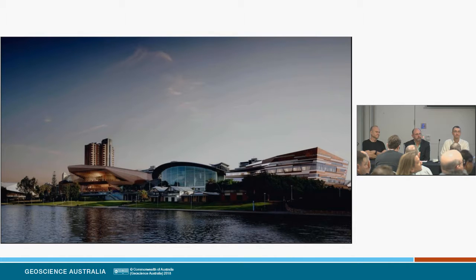Hi Mark, Matt Zenger from Gondwana Geoscience. Question for you, just regarding your Fourier and your equivalent source presentation. Bearing those two types of things that you explained in mind, what is the strategy you might employ when merging data sets together that come over different types of terrain, low and high terrain, where you've flown one with one type of survey, and one with another? Which is the strategy you think is best employed?